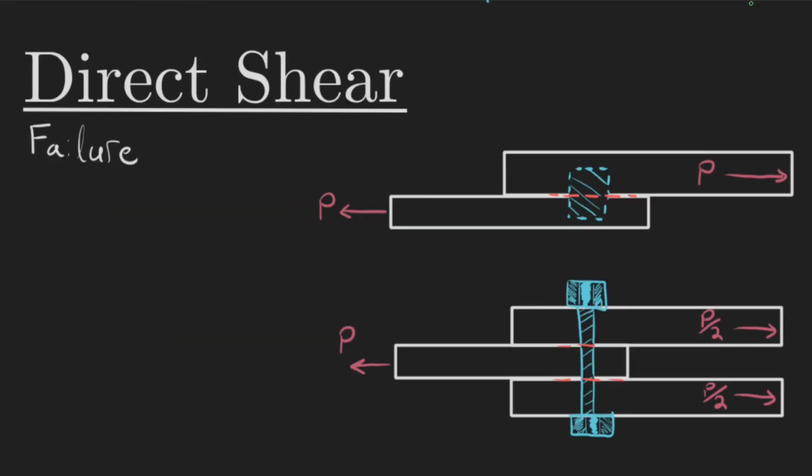and then this would be the design factor of safety. Now let's go ahead and take a look at how a direct shear stress would work. So basically the idea here is that the plane that's taking the shear stress, so remember that if we have our little cube here and we have a force on top, then what that's going to want to do, if this is our bearing area, or the area that's taking the load down here, it's going to basically want to turn it into a parallelogram like this, right?